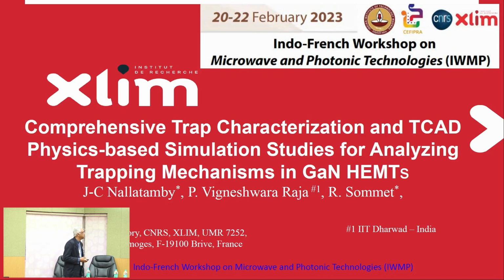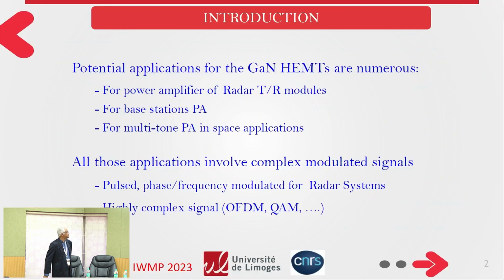My talk consists of comprehensive trap characterization and TCAD physics-based simulation studies for analyzing trapping mechanisms in GaN-HEMT, and also reduced NT, as we will see later. The potential applications of the GaN-HEMT are numerous, as you know: power amplifiers for base stations, multi-tone power amplifiers in space applications. All those applications involve complex modulated signals, pulse phase, and also highly complex OFDM signals, as presented by Jacques Sombrun this morning.